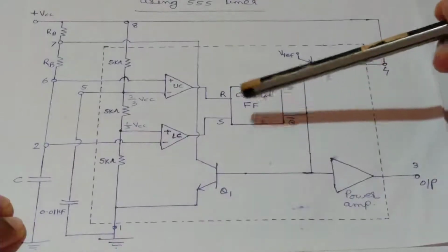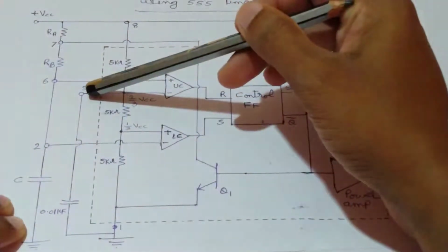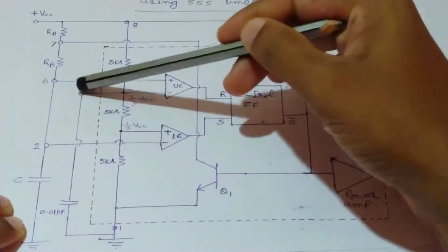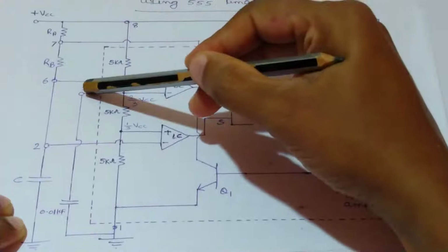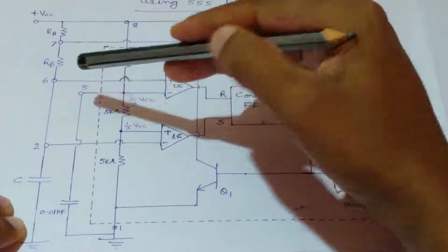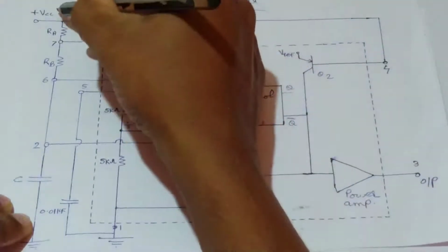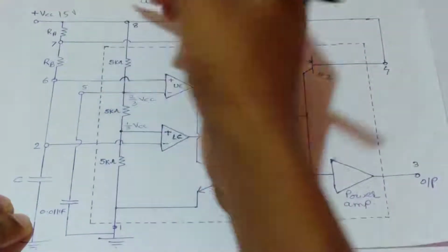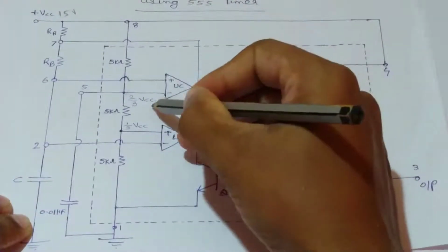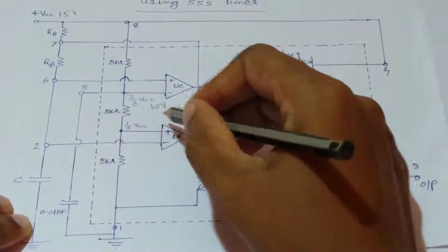This is the functional diagram of an Astable Multivibrator using 555 timer IC, and when we need to use this as a pulse position modulator, we need to connect that modulating input signal to this fifth point, and this capacitor section is not present. Here a triangular wave is applied to this fifth pin, and what will happen when that triangular voltage is increasing? To understand that, consider an example. Consider the VCC voltage applied here is 15 volt. Then here we have 2 by 3 VCC voltage, 2 by 3 into 15, that will be 10 volt. And here we have 1 by 3 VCC voltage, that will be 1 by 3 into 15, that is 5 volt.